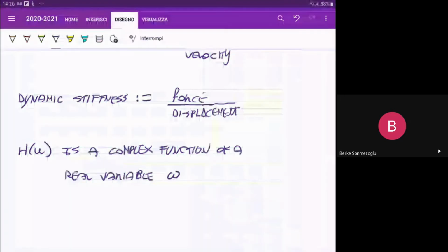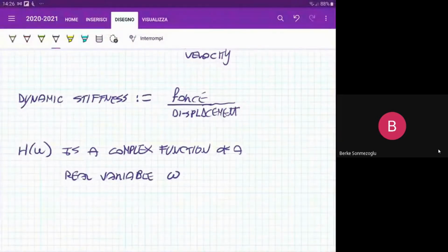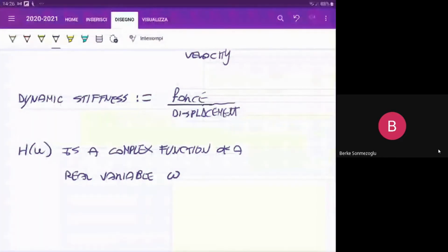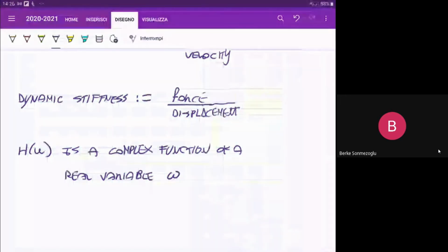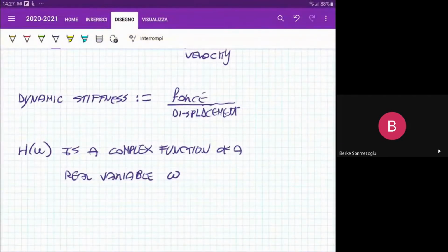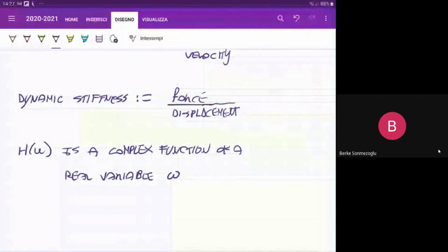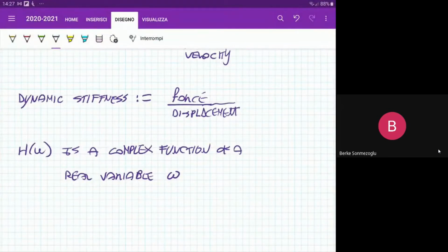Why that? Because we already discussed that the negative side of your frequency response function is not considered, because first, we know perfectly what's happening to the negative side. There could be a symmetrical or anti-symmetrical function with respect to the positive omega axis, according to the different part of your FRF. And the contribution of this negative side FRF to the actual peak resonances, for example, is negligible. So that's the reason why we are not considering that when we are analyzing your system response.